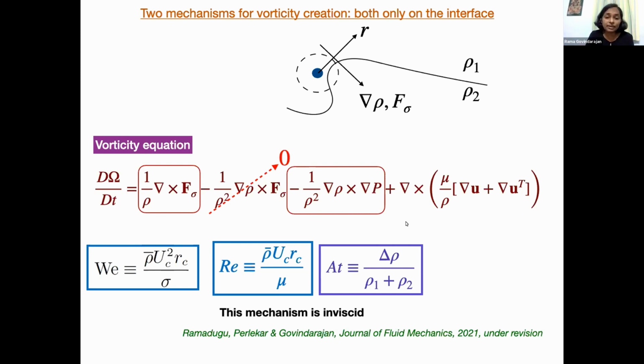So even in the inviscid case, our mechanism is actually inviscid. If we understand the inviscid problem, we've understood the problem. Viscosity doesn't do too much to change the answer qualitatively. We do have a Reynolds number because we have run 2D simulations at finite Reynolds number. But we're going to do the analytical work at infinite Reynolds number, and they're going to qualitatively give the same answer because there's no particular way in this problem in which this term acts as a singular perturbation. So we can happily study inviscid and understand high Reynolds number.